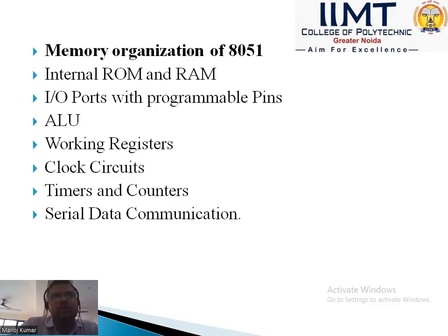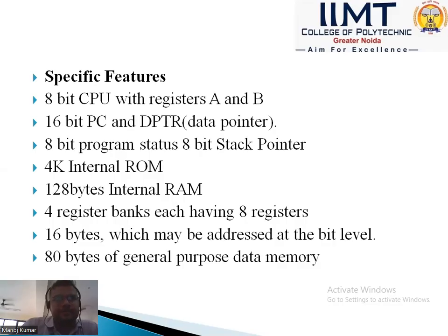Okay. Input-output ports with programmable pins, arithmetic logic unit, working registers, clock circuit, timer and counter, and serial data communication are classified in further slides. Specific features: 8-bit CPU with registers A and B, 16-bit PC and DPTR data pointer, 8-bit program status word, 8-bit stack pointer, 4 kilobytes internal ROM, 128 bytes internal RAM, 4 register banks each having 8 registers, 16 bytes which may be addressed at the bit level, and 80 bytes of general purpose data registers.